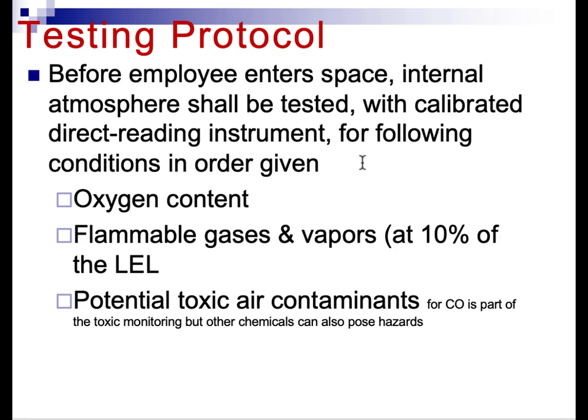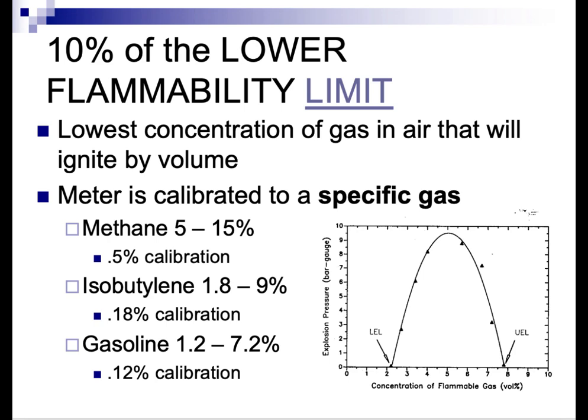So our testing protocol: before an employee, an entrant, enters the space, we monitor that space with a calibrated direct reading instrument, and we monitor for oxygen, flammability, as well as any potential air contaminants. So we set our meter to a specific gas.